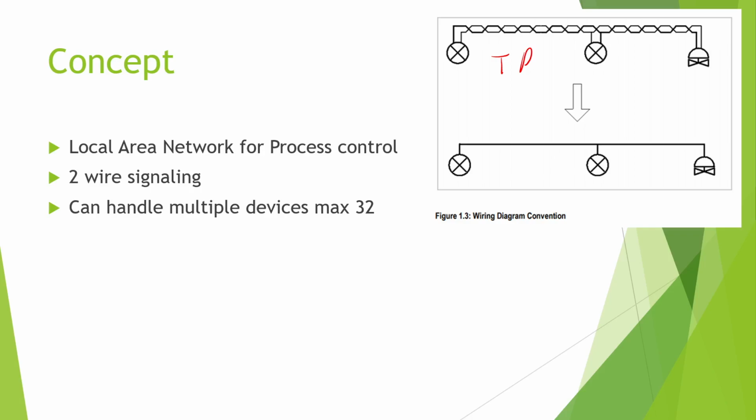All right. So that is what's known as a one-line diagram in the world of electricity. If you have a device A connecting to device B, and it's over a standard protocol or something, like okay, I'm not going to draw every single wire. The person reading this diagram, as long as I tell them that this is such-and-such protocol or system, they should be able to go, okay, there are this many wires going in there.